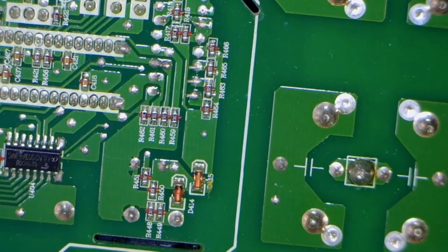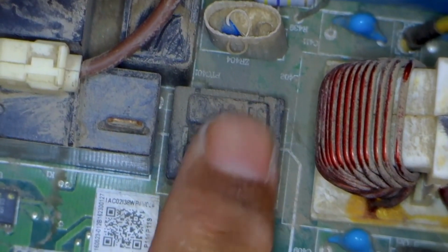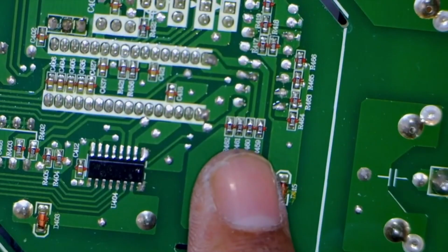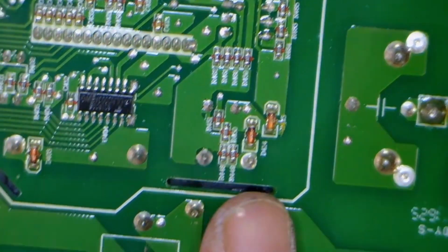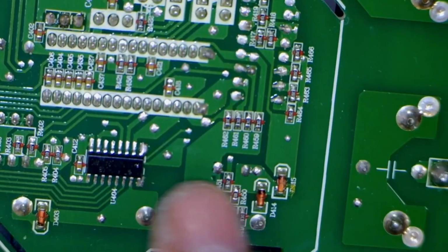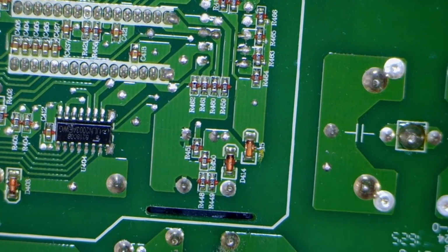However, it's important to ensure that the installed current transformer is functioning properly. By chance, if the CT or current transformer is okay, then the fault could be in the current detection circuit. Also, I have experienced that if short circuits happen, the microcontroller becomes faulty, and other functions of the PCB work correctly. Still, the current detection circuit or microcontroller does not work properly, but that happens very rarely. If it's okay, then there is no problem.